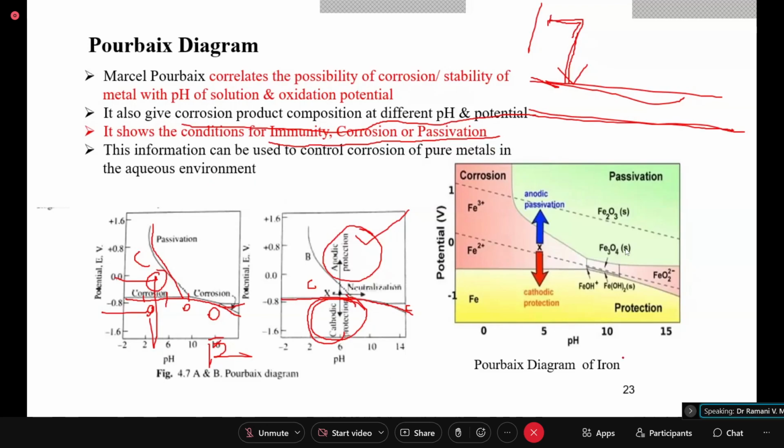But this particular system is for iron, which is studied very much in detail. Now, a more enlarged figure or better understanding is developed how you can passivate it. Iron can be passivated by rendering it anodic, but the potential range in which it remains passive is small. So this is the cathodic protection region, and this is the corrosion region where corrosion would be taking place. So this is the Pourbaix diagram.